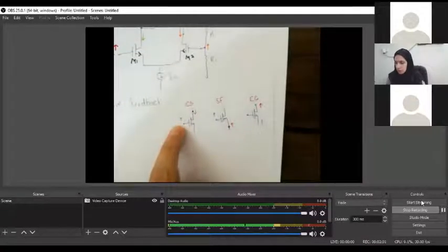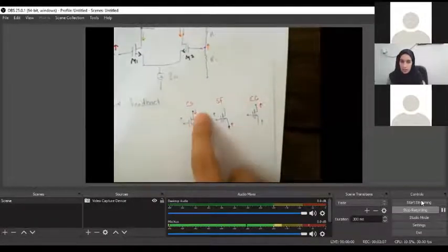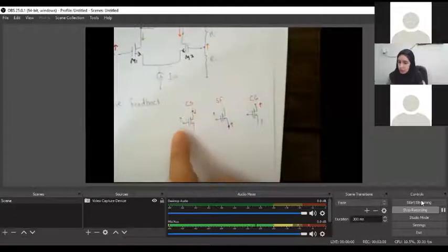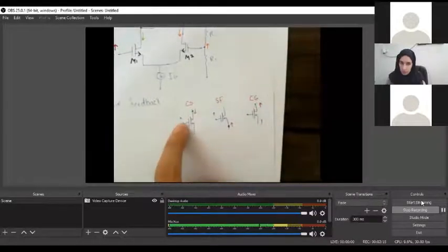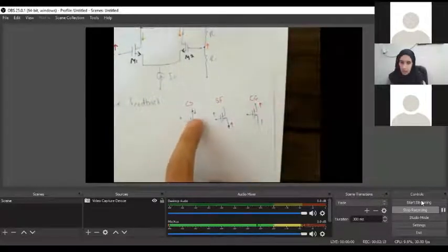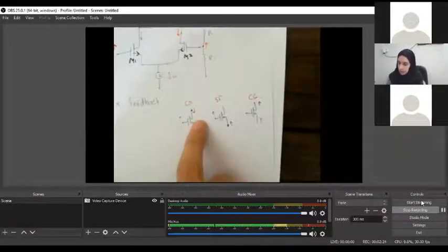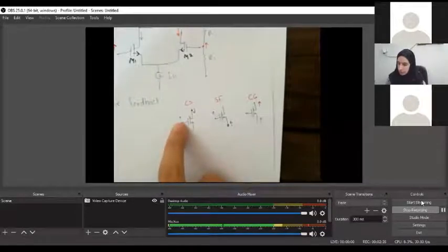If you assume your input is being increased on the gate, and you are checking at the drain, the common source has a negative gain, minus gm RD. So if you increase your input, at the drain you expect the output to drop. We must know this: input at the gate, checking at the drain, input increases, the drain is going to drop.